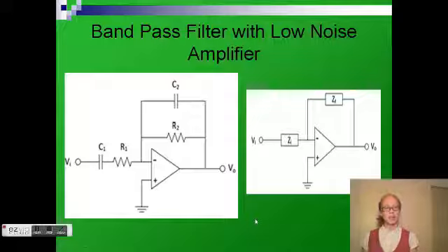As for our bandpass filter and our low noise amplifier, this is our circuit. Obviously we can tell from a glance because you look at it and you say, oh, capacitor. Capacitors are open in DC range, low frequency, and act as shorts in high frequency. Therefore, at low frequency, this will be turned off, and this will just remain 0, and at high frequency, these will be shorted.